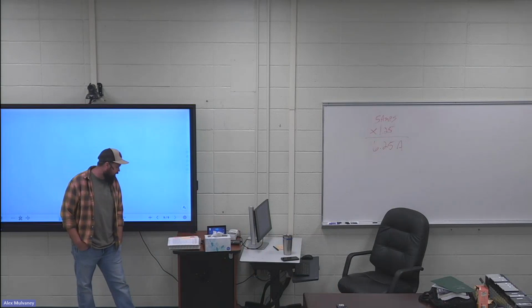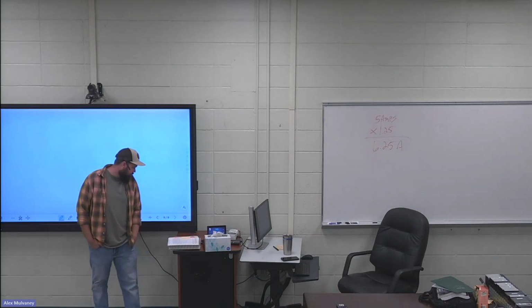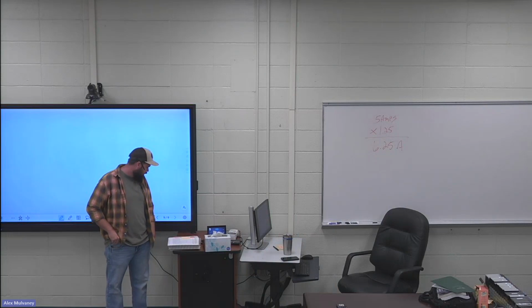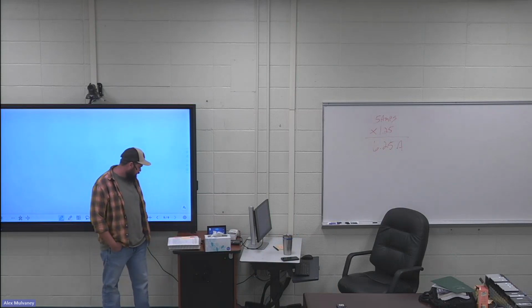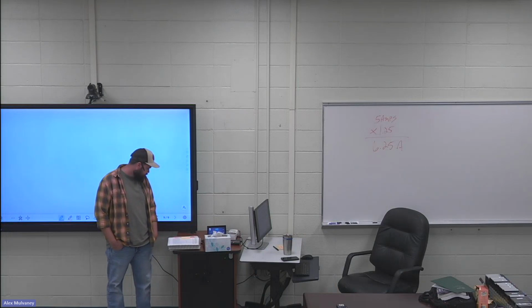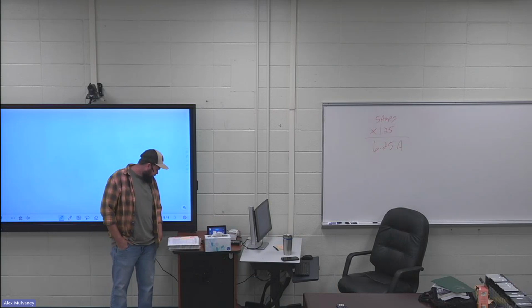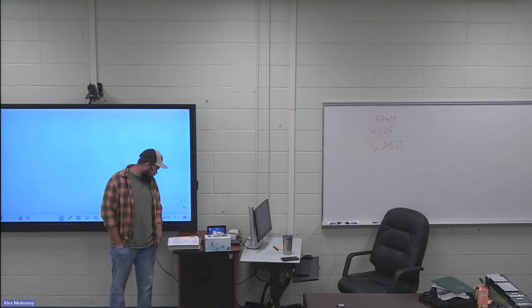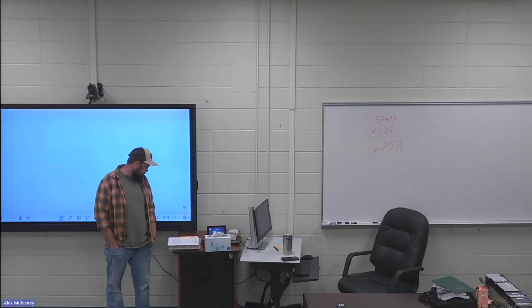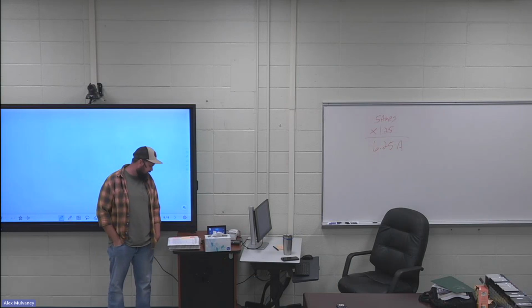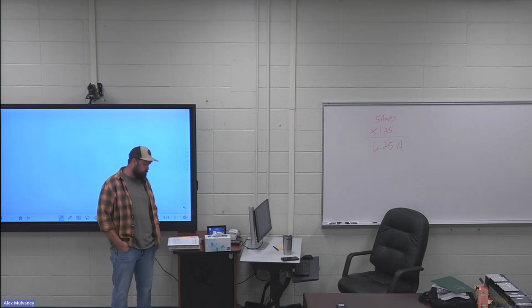So example 3, 1 wall-mounted oven and 1 counter-mounted cooking unit are to be installed in the kitchen. To reduce the cost of the electrical installation, both pieces of cooking equipment are to be connected to the same 240-volt single-phase circuit. One oven has a nameplate rating of 12.5 kilowatts, and the counter-mounted unit has a nameplate rating of 8 kilowatts. What is the demand load in amps for a single circuit to supply this cooking equipment?